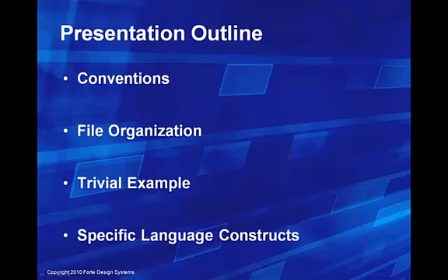We'll start off with some of the conventions of SystemC and talk about how we commonly organize our code into multiple files. Then we'll look at a small example implemented in Verilog RTL and in SystemC behavioral code, something appropriate as input to a high-level synthesis tool, which is the main design path for SystemC coders. Then we'll end up with a rundown of some specific language constructs.